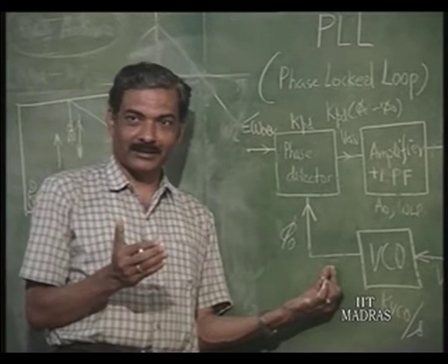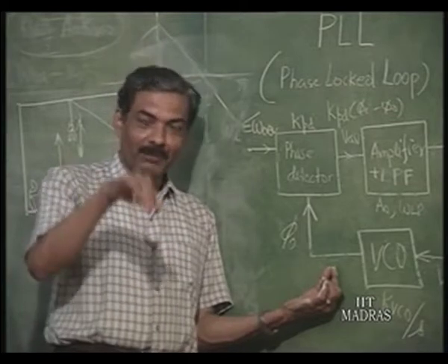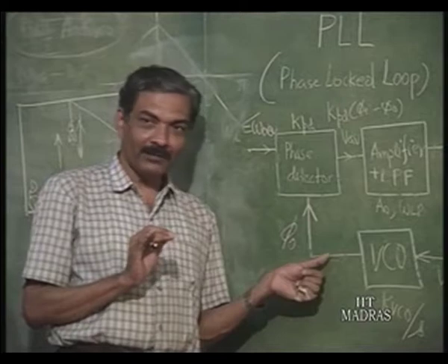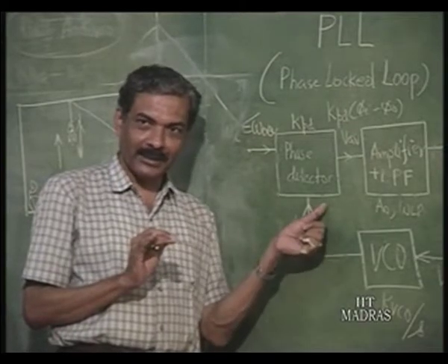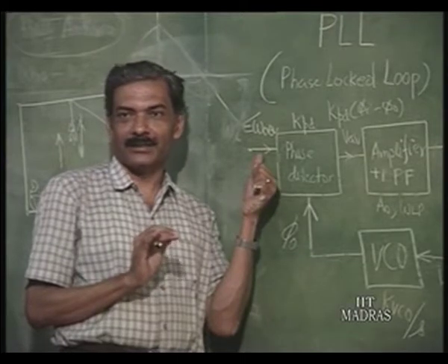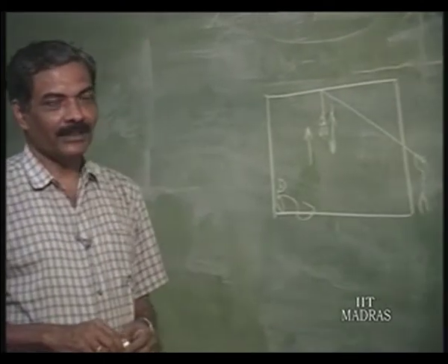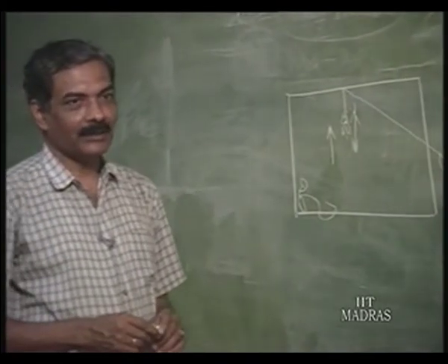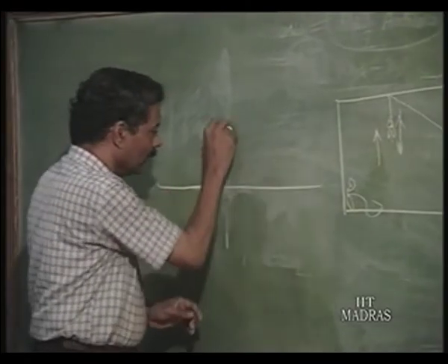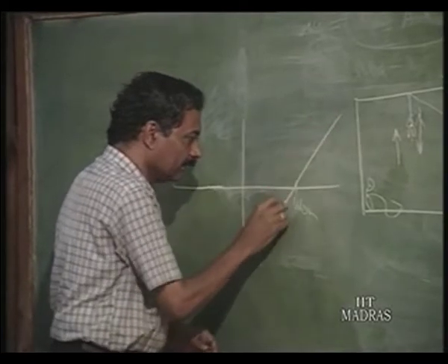All are assumptions which are not really valid strictly, but the probability of capture is going to be high only when the swing from the quiescent here is such that it reaches at some instant of time the incoming frequency. So, that is roughly going to be the capture range on either side of omega naught q. So, if this is the lock range,